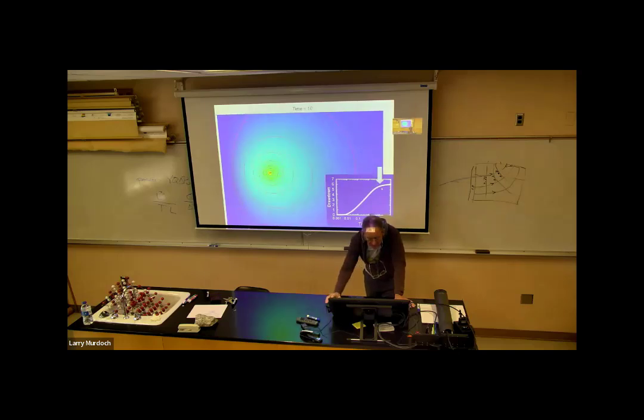So we keep going in time. You see this flattens out even more and extends out in this direction. And this flattens out even more. And then we go out in time yet, and this is flattening out even more. In fact, this looks like it has flattened out and the slope is essentially zero. So if the slope is zero, that means that the drawdown is not changing with time, and that's the definition of steady state.